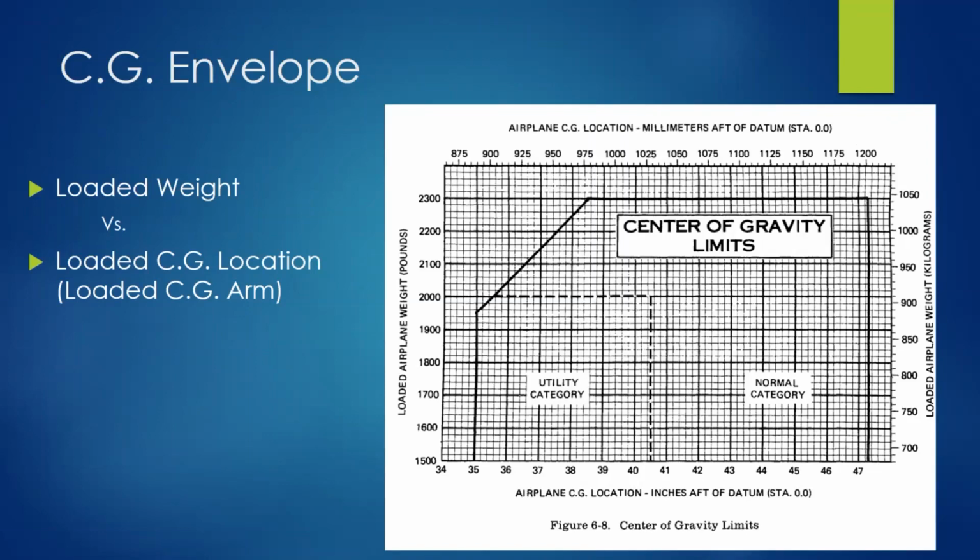And that's why it's also easier to recover from like a stall, because you can get the nose to point down easier, right? Because how do you recover from a stall? Full power, nose down, right? And what? Throttle forward, nose down. That's the basics I know of it, okay? So you try to power out of the stall. So you have to have that weight forward to be able to get that nose to come over, okay, or out of a spin.